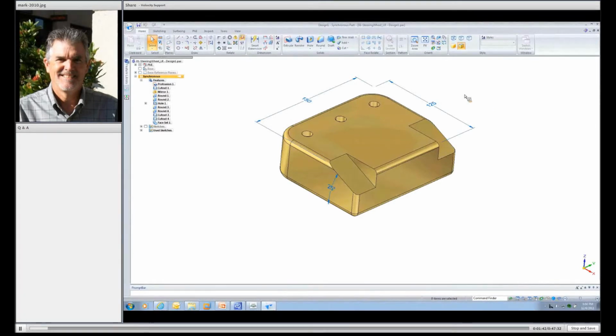As I move my cursor over the model, you're going to notice that different faces highlight. And if I click on this top face, you're going to notice immediately a couple of things occur. First of all, the face is going to highlight, but more importantly, the initial state of the steering wheel is going to appear, allowing you to grab that, in this case the arrow, and move that face up and down. Also, which will appear on the bottom of your screen down here, is what we refer to as live rules. Live rules monitor this model as we make changes to it, as we move faces.